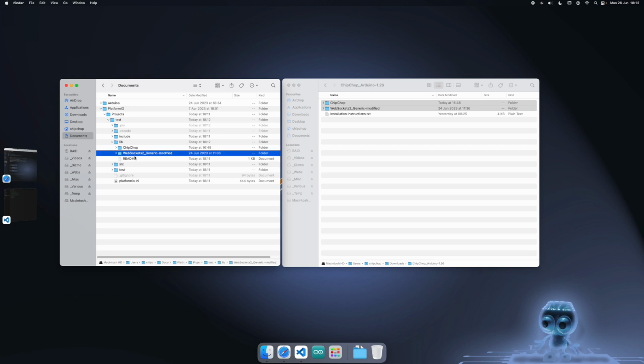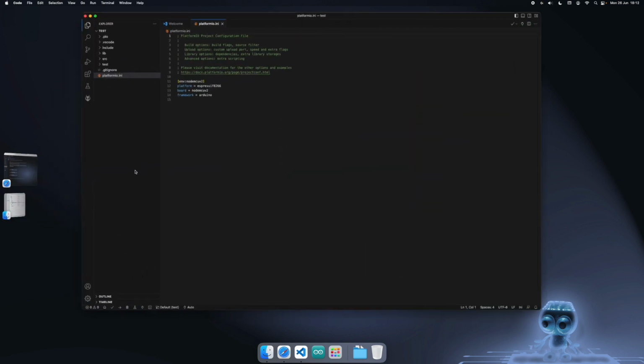And this is the only difference between the installation with Arduino IDE and PlatformIO. We are now manually including also this WebSockets2 generic library. The reason for that is that this is a cut-down version that is optimized only for the ESP8266 and ESP32 boards, because the full library does not behave that well with PlatformIO. The full library supports all sorts of boards, and for some reason it doesn't want to compile that nicely under PlatformIO. And I've spent some time extracting the parts just for the ESP8266.